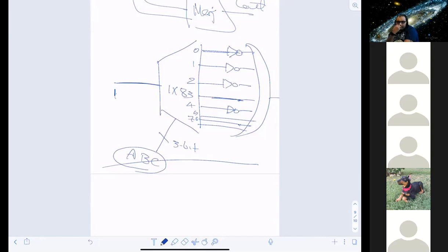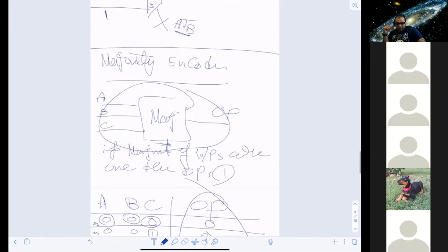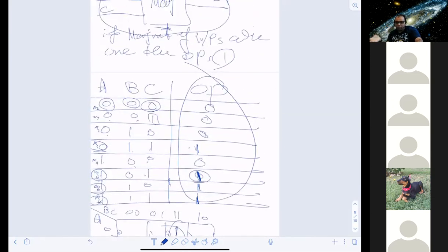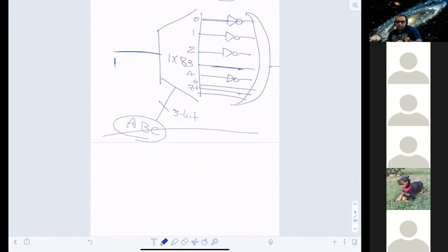If we only have a 2-bit selector, wouldn't we need 2 multiplexers? If we had only 2 select bits, the number of outputs would only be 4. Yes, you can either build it with a bigger one or take care of it. I made it here in front of you for the 1-bit full adder with a 4-to-1 multiplexer. You can make it up to 8-to-1 in this case because it's three inputs. You can also make it with 4-to-1 multiplexers.